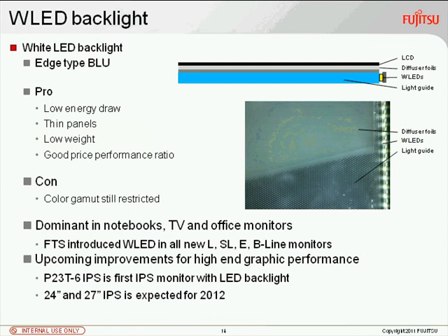should show the glass plate, and upon the glass plate there are diffuser foils, and after the diffuser foils you have a homogeneous white light, and this goes into the LCD module, which makes then the picture. Here below you see a photo of this. So here you see the LEDs, these bright dots here, and the small dots, this is the front of the light guide. The light guide has mirror foils on the rear side and on the top, and only small dots are not mirrored. And these small dots let the light out to the front.